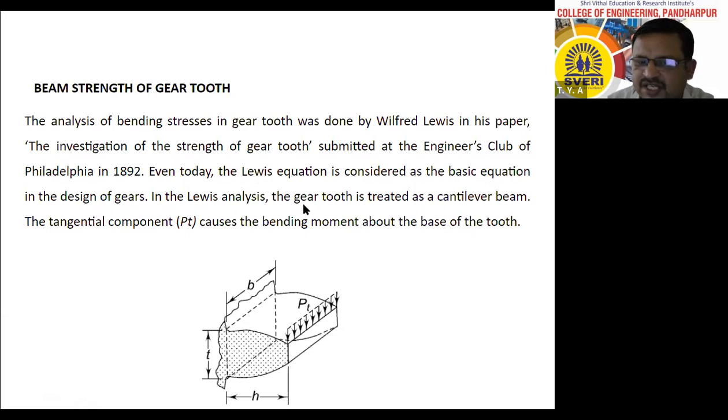Now, in the Lewis analysis, the gear tooth is treated as a cantilever beam, and the tangential force causes the bending moment at the base of the tooth.